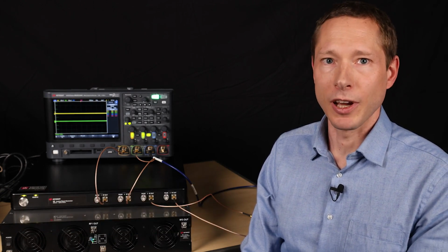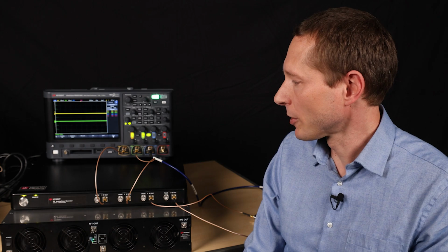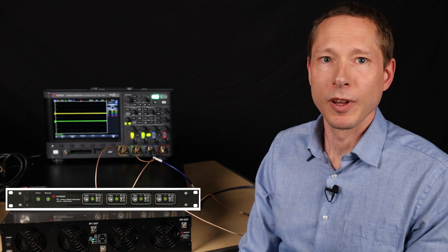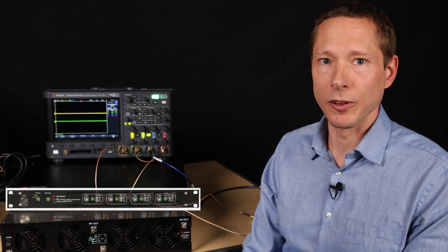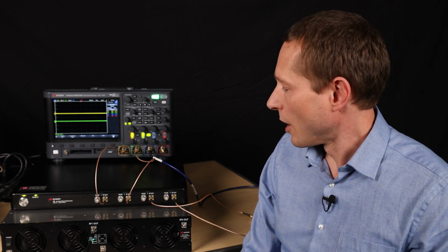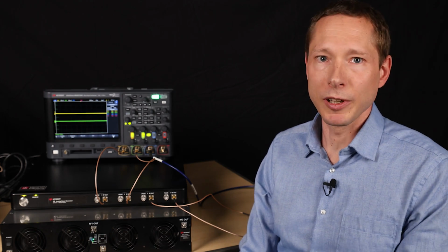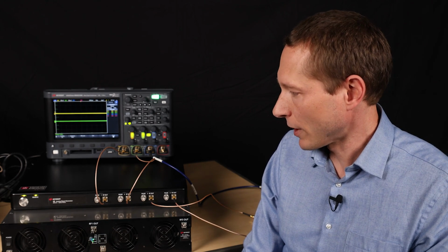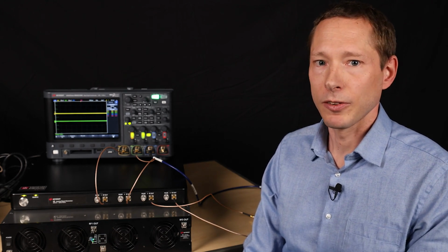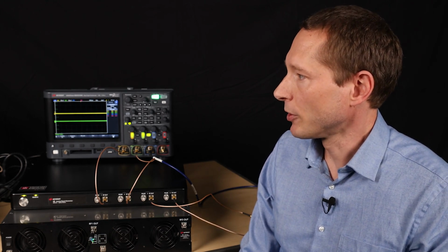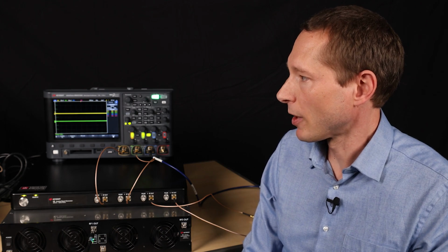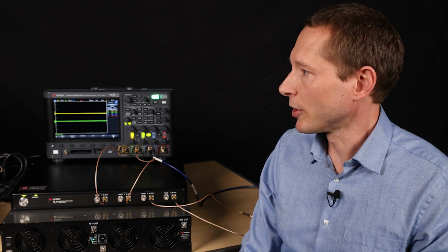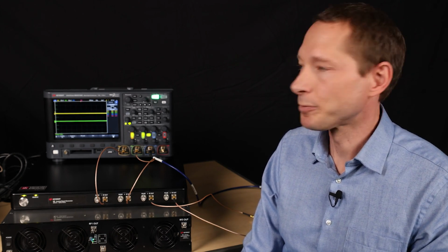In this presentation, I'm going to show you how to use our multi-channel analog signal generator AP5012 to generate fast pulsed list sweeps. This multi-channel unit has the capability of running individual list sweeps on all of the 4 individual channels with a tight timing control. We can use this to generate sweeps that produce pulses with individually configurable timing.